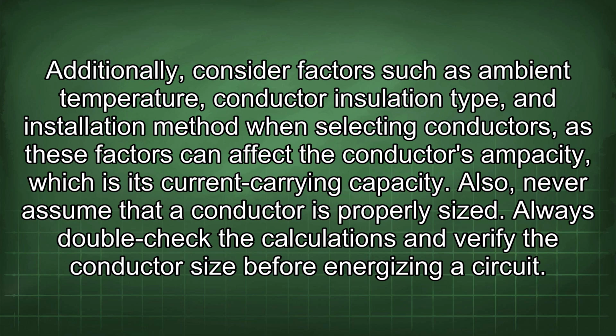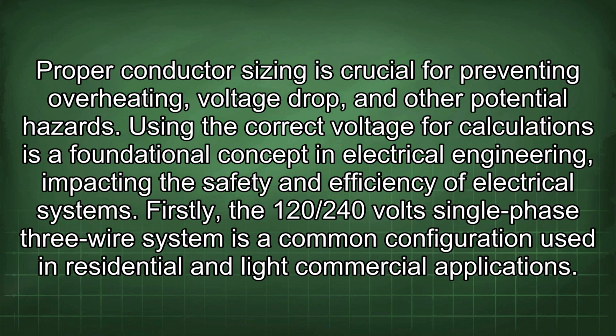Also, never assume that a conductor is properly sized. Always double-check the calculations and verify the conductor size before energizing a circuit. Proper conductor sizing is crucial for preventing overheating, voltage drop, and other potential hazards. Using the correct voltage for calculations is a foundational concept in electrical engineering, impacting the safety and efficiency of electrical systems. Firstly, the